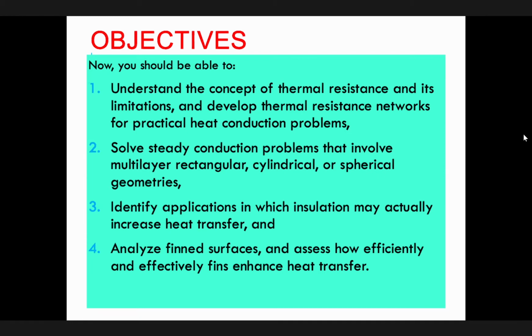If you would like to increase H, it means you have to increase air movement. Therefore, you have to use a bigger pump, a bigger fan, and so on. And A, you cannot have a 1 kilometer heat exchanger because it's not economical and you have no space. Therefore, you add the fin in order to do that, okay? This is, again, the other side of the conduction that you have to learn, okay?